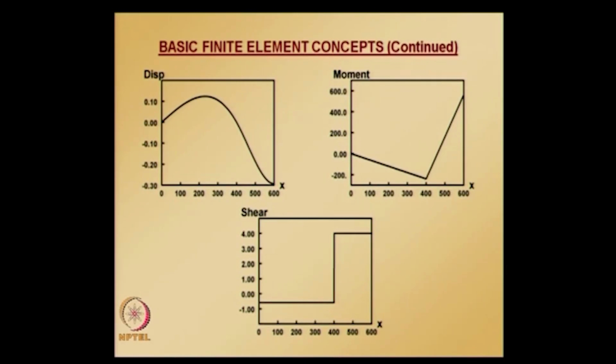If you are concerned whether the values that you computed are correct or not, there is always a check for verifying the results, and to do that it is instructive to draw free body diagrams using bending moment and shear at element ends.